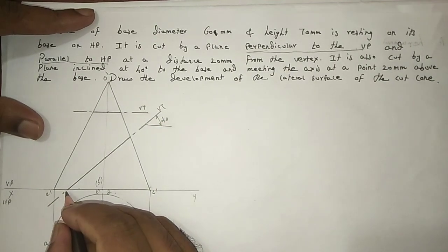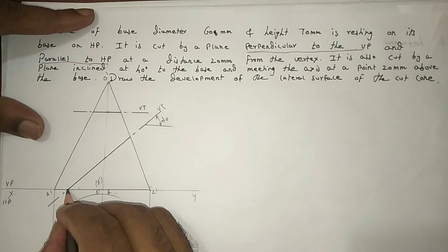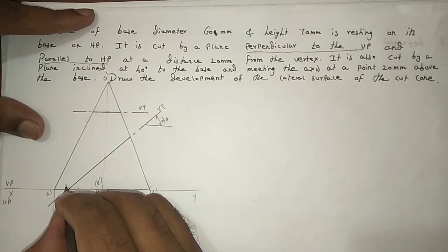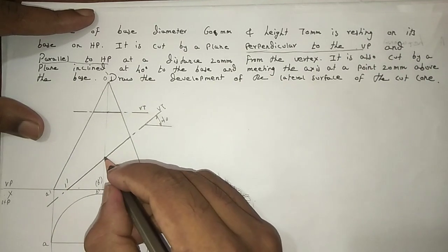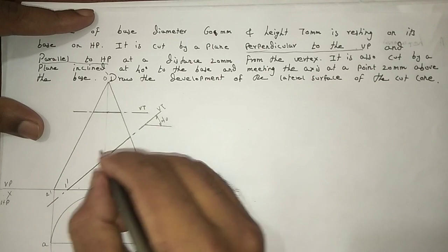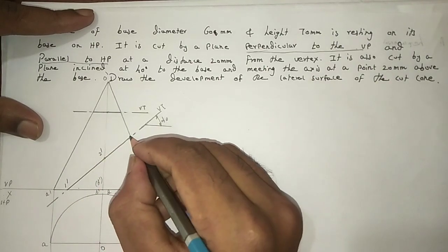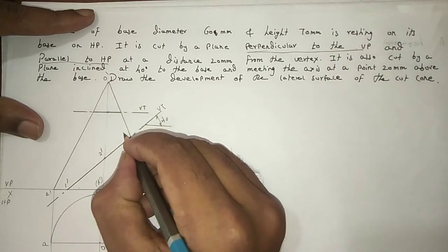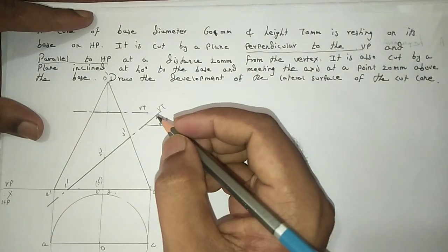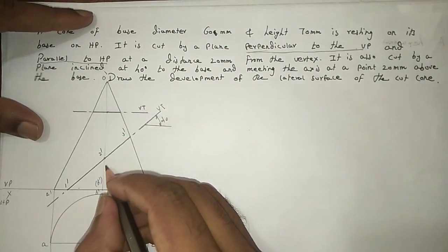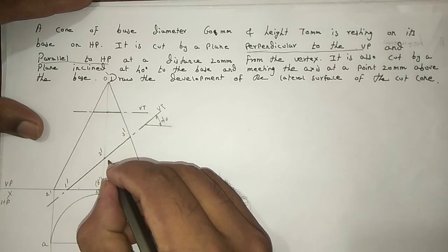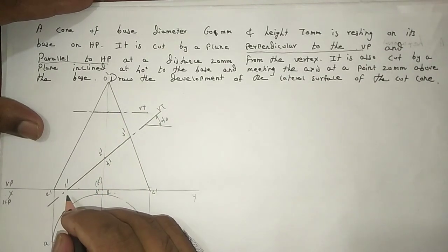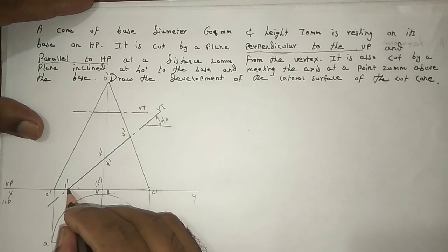Okay, and next I am going to give the numbers on the section plane. Here we start from here. The cutting plane cuts the cone on the base. So this is the first point, 1 dash, and the second point is through the axis. So this is 2 dash. The third point is on the slanting edge. This is 3 dash, and the fourth point is again the center of the axis, behind the edge, the invisible edge O and D. So here 4 dash, and again one more point is there. The section plane cutting on the base.